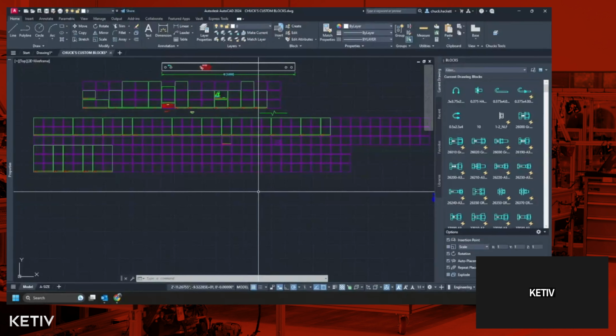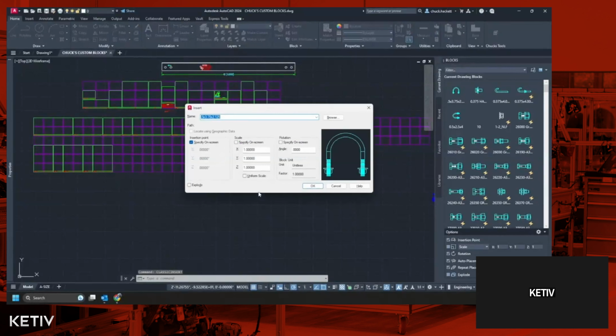Well, for those of you who want to know how to do the classic insert, because I want to compare the two, I'm going to show you the old way. For those of you that are command line warriors, you've probably already picked up that I tend to choose my words carefully on here. If you want to go back to the classic insert at your command line, you're going to type in classic insert and push enter.